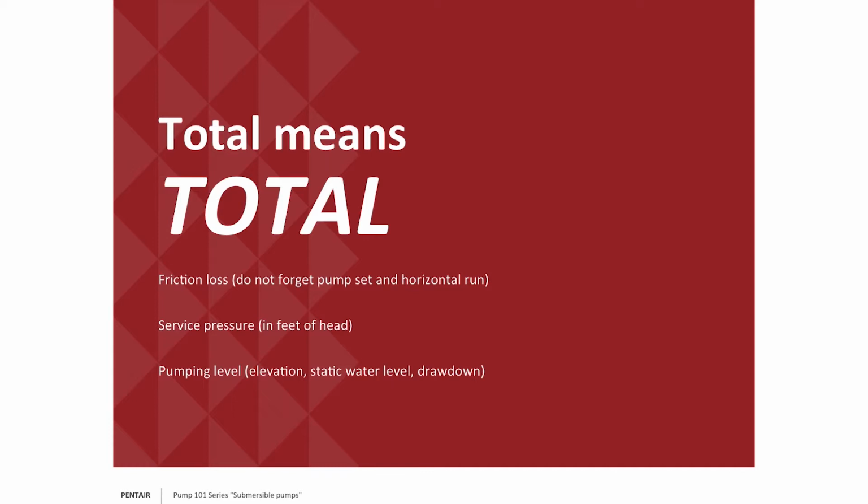So we shouldn't always assume, but we do assume that when you say total dynamic head, it means that you've taken into account all your friction losses, you've taken your service pressure and converted it into feet of head, and that your pumping level, which includes the elevation of the situation, the static water level, and the drawdown, have all been accounted for.